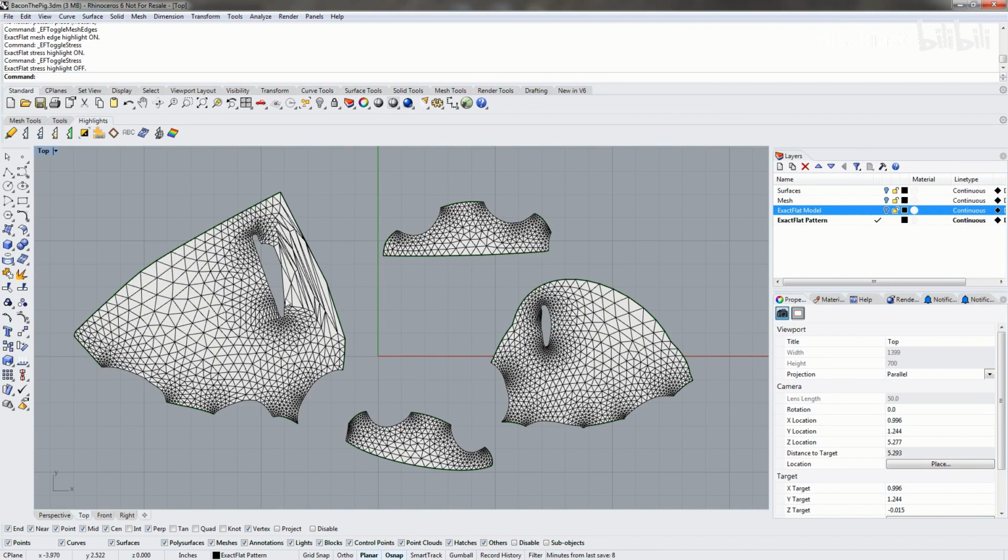If the shape of your pattern piece is very important and you can't or you don't want to use a pre-flattener, then you can use the automated flip triangle removal tool. It will attempt to remove flip triangles without altering the shape of the pattern piece. And lastly, the third method is to do manual vertex manipulation, and this allows you to manually drag vertices of triangles to change the orientation of the triangle.